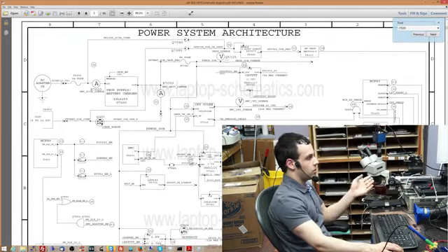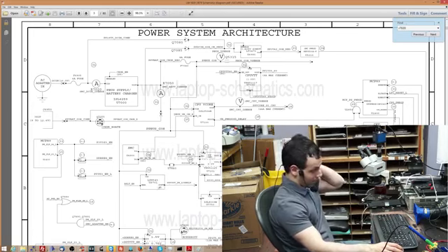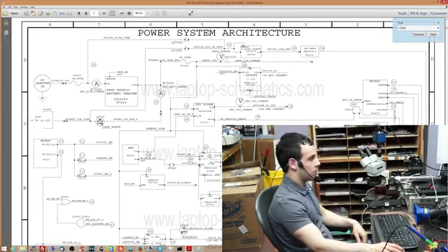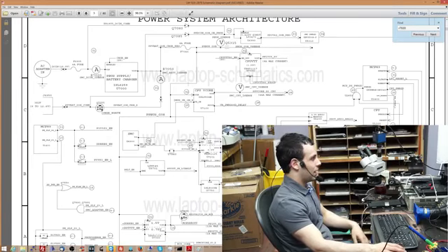Then it'll tell you something like the power system architecture. Again, this is handy. The power goes to this chip. This creates power for the rest of the machine. This creates PP bus G3 hot. It talks about the CPU vCore rail. It talks about the backlight rail, where that comes from. It gives you a basic little breakdown of how a lot of things work. But I don't really go back to look at this very often.